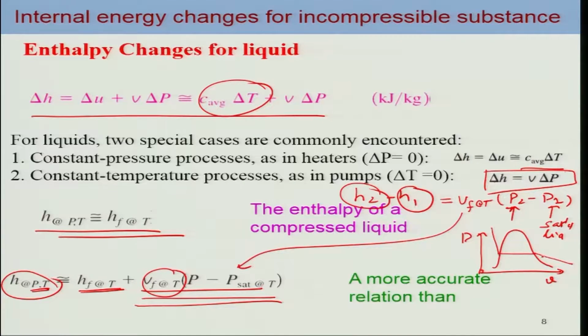So liquid, and it evaporates at a constant temperature when you reduce the pressure. What we are assuming is that for the specific P and T, this particular enthalpy at this P and T can be approximated by this value plus the change in the pressure, delta P, multiplied by the corresponding V for the specific T here, which is this.